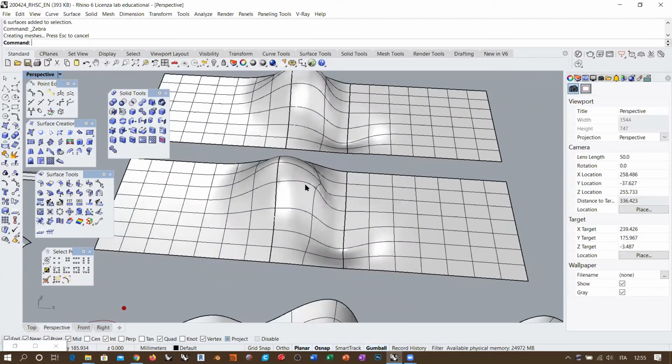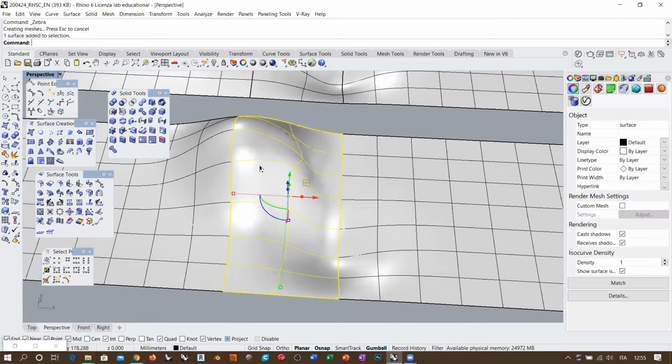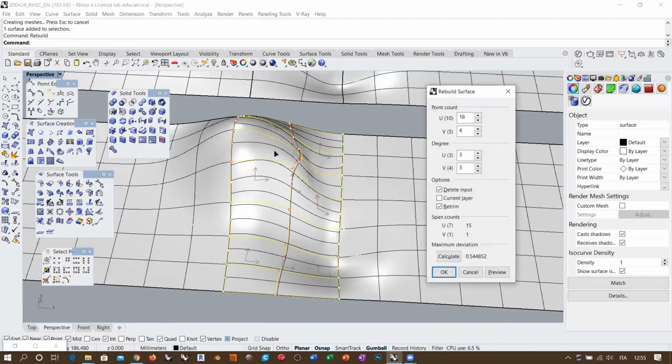We were expecting this. What happens if we analyze this surface and we take a look, for example, at this degree? V is actually made up of 5 control points. But if we take the degree, it says 4. Now, this is something that is absolutely problematic, okay? We said that we don't want to work with a degree which is higher than 3 normally, okay?